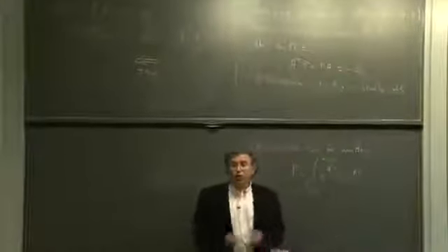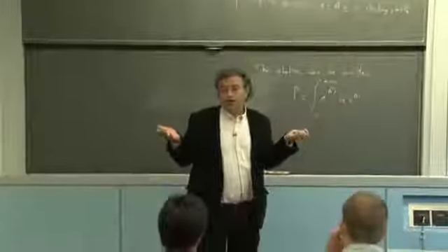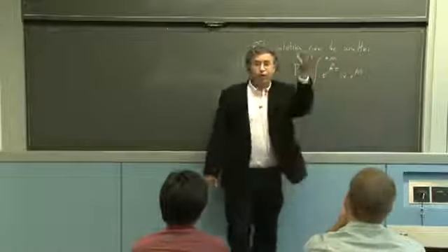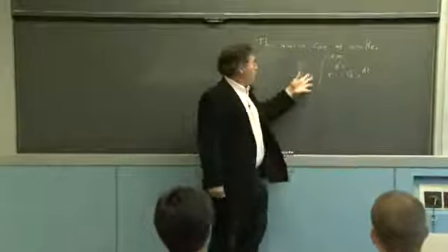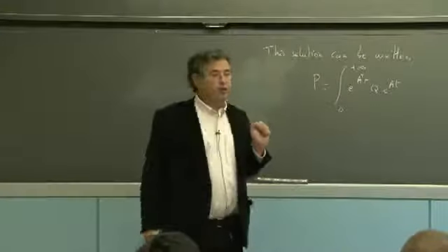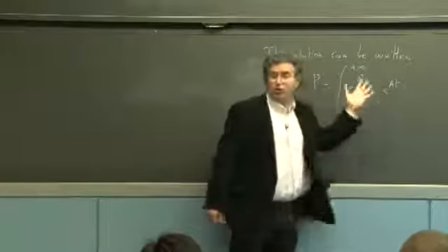Even if you take a scalar system, suppose you had x dot equals 2x, then this infinite integral would be blowing up on you. You wouldn't have a constant matrix P. So the very fact that we can write this fundamentally uses the assumption that A is stable, so that these are basically decreasing exponentials.